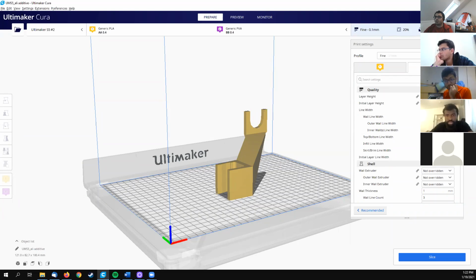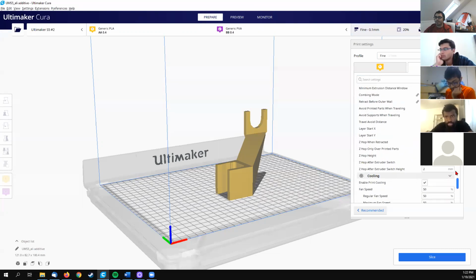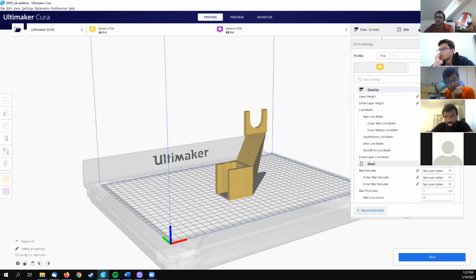And this is usually supports off. And this is also additional base material. So what this is, is that there is extra material added around the part to increase the area footprint of the part so it sticks better to the bed. So when you see these, you have an idea of what the setup is, but all the parameters are actually in this long list here. And you should be careful that this long list is now for nozzle number 2, but we're working with number 1. So we click here, and now we switch to the nozzle we need.